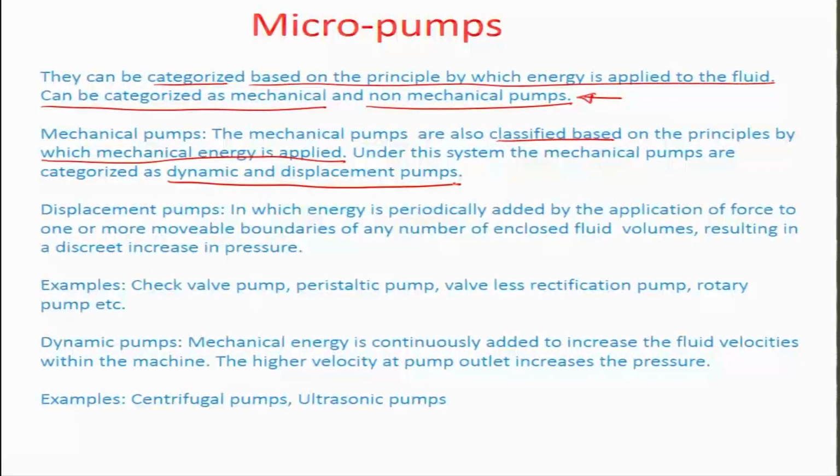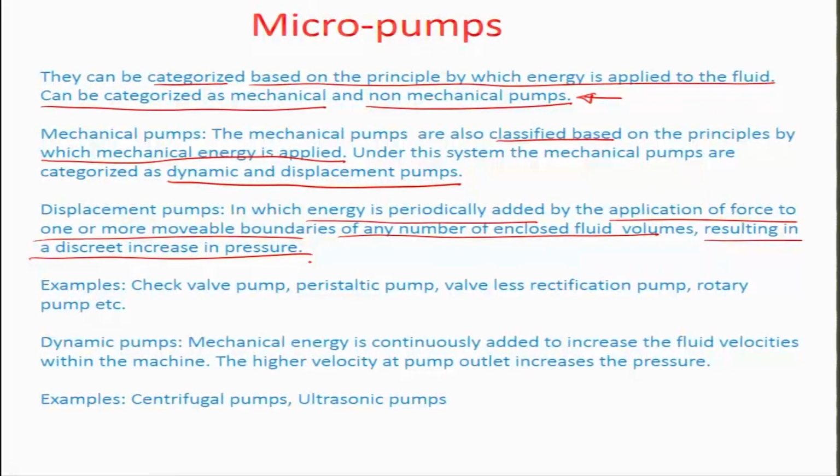In dynamic pumps, we are talking about a rotary component mostly, and in displacement pumps, we are talking about a piston-based linear movement of the actuation mechanism. The displacement pumps are ones in which energy is periodically added, probably by application of force to one or more movable boundaries of any number of enclosed fluid volumes, and this results in a discrete increase in pressure, because of which fluid is forced to go out.